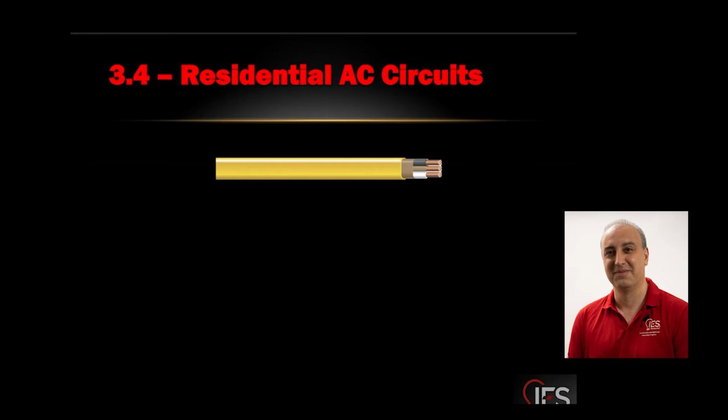Do you know what size wire this is? 12 gauge. That's correct. Is it 12-2 or 12-3? 12-2. Why is it not 12-3? I see 3 conductors in there. Well, you only have one hot, one neutral, and one ground. So the two, but you're on the right track.